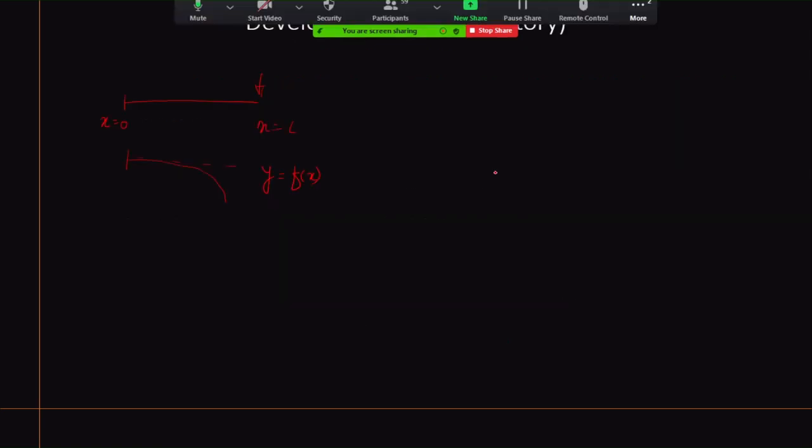In this case, you can take this as your entire domain. I can divide that domain into multiple points. This is called discretization. I can now separate out one single element and put in its behavior. That behavior is represented by d2y by dx square equal to M by EI. This is the beam bending equation.